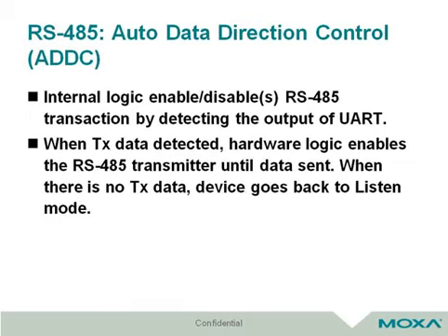The other is a Moxa patent technology named Auto Data Direction Control, ADDC. In ADDC, hardware will control the data direction automatically. When there's transmit data detected, hardware logic enables the RS-485 transmitter until data is sent. And when there is no transmit data, the device goes back to listen mode.